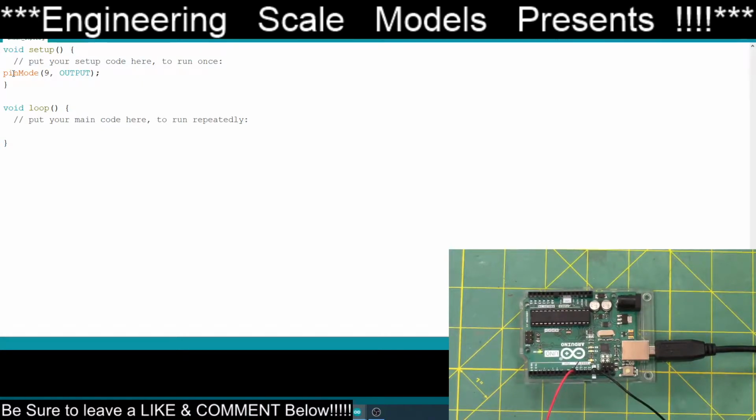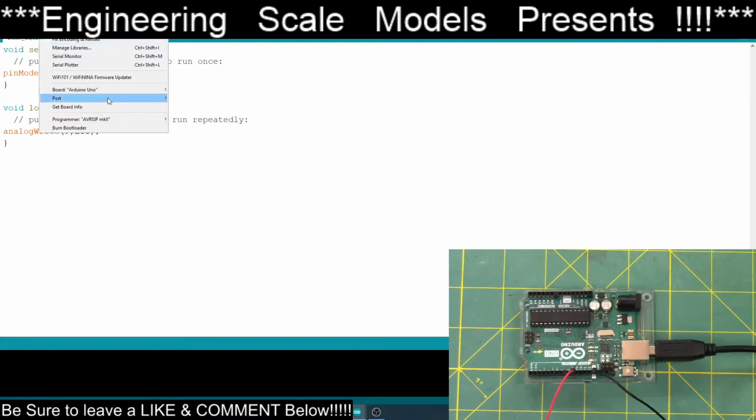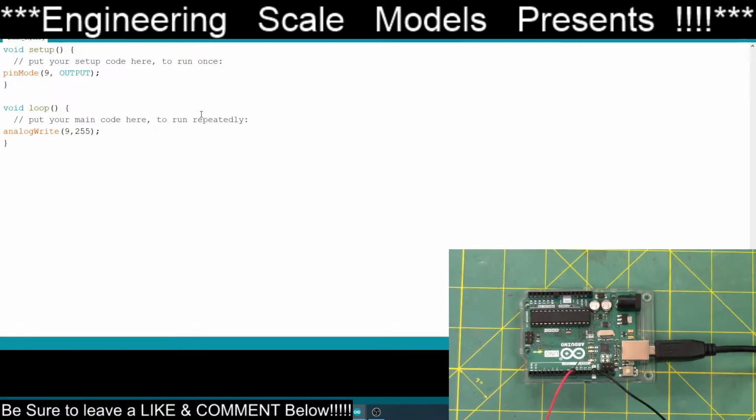And then we are going to do an analogWrite, and we are going to write pin 9 a value of 255, and we're going to look at that on the oscilloscope. Let me make sure my Arduino is connected to the right port, because we all know that gives me issues.